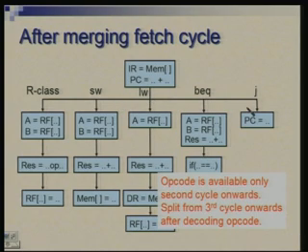Before we can split, we need to see what the opcode is and which instruction or instruction group it is. But you can start looking at the opcode only after you have fetched the instruction and brought it into IR. Okay. So, now the instruction is available to you from the second cycle onwards, and therefore, you can start looking at the opcode from the second cycle onwards.